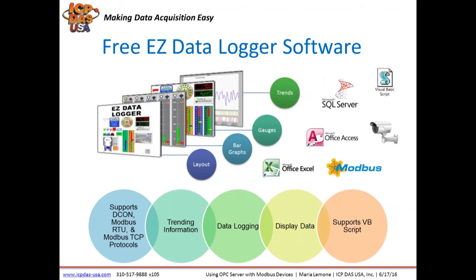WinGraph is software that we provide for some of our ViewPAC and WinPAC controllers. It allows you to program in ladder logic, structured text, instruction list, sequential function chart, and also function block diagram. And it runs on newer Windows systems like Windows 7, 8, and 10.